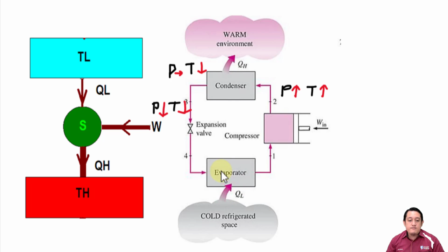receive heat from the cold refrigerated space. So that means the refrigerant will absorb the heat. What will happen if a liquid absorbs heat? The liquid will change its phase to gas. So that is what is happening inside this evaporator.